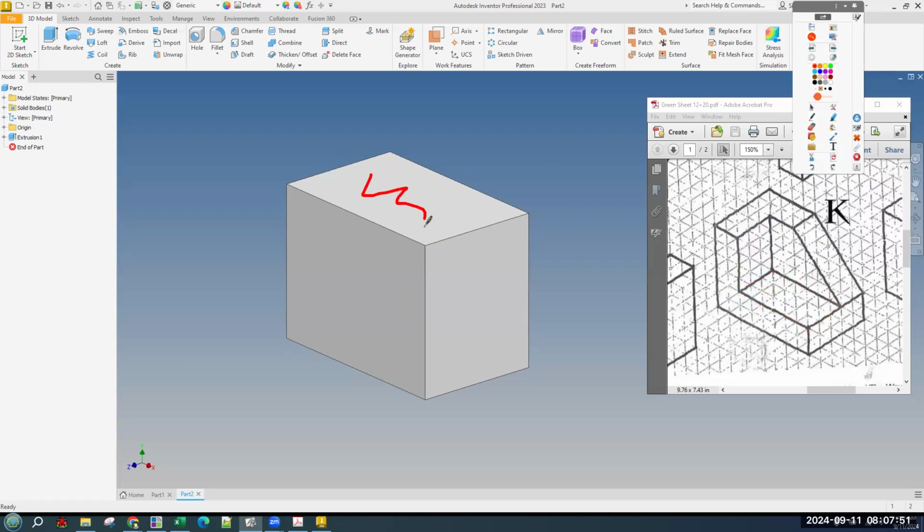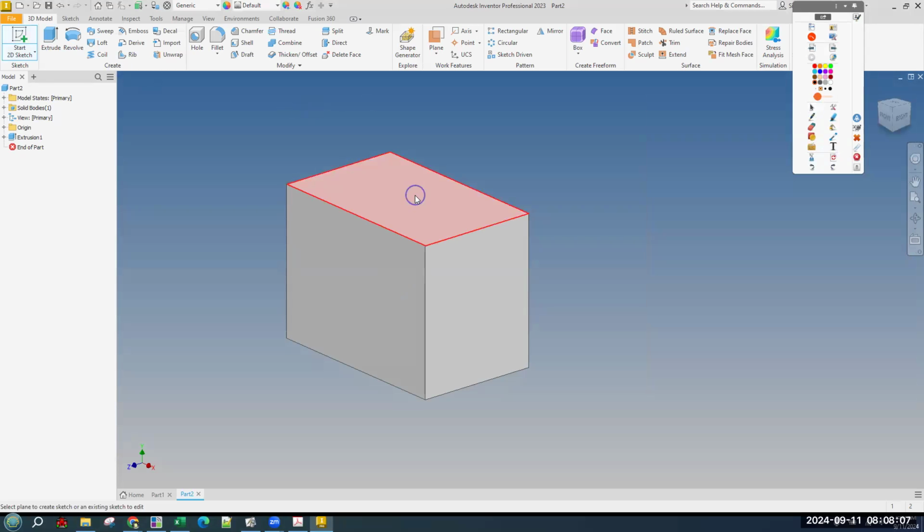So we're going to sketch on the top face, and we're going to make a rectangle that is 3 front to back and 6 along the long way. And then we will cut extrude 4. So 3 by 6, cut 4. Sketch on the top face.